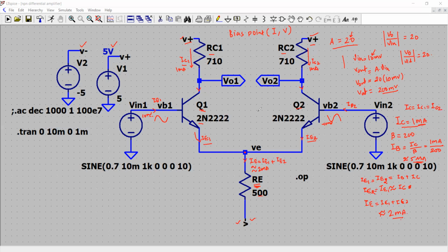Now, I have, let's say, the V plus, that is 5 volt coming over here, and I would like to have the DC bias level at the outputs. So remember, when I'm doing the analysis for one branch of the circuit, for example left or right, it is applicable to the other branch because the circuit is symmetric.